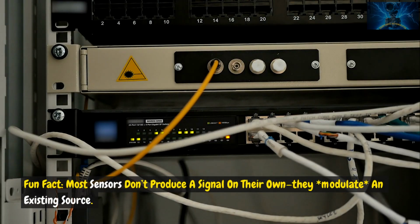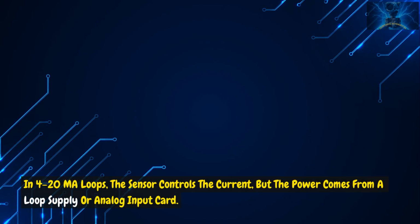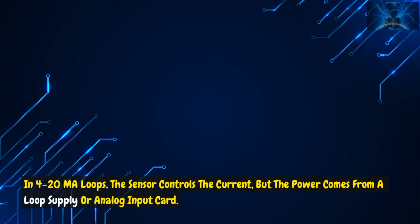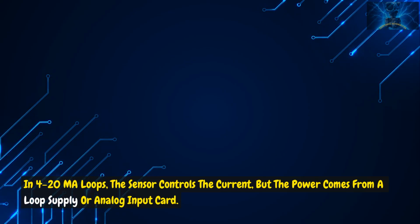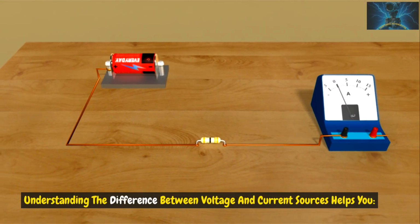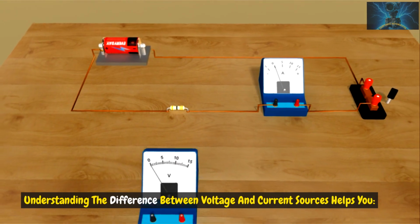Fun fact: most sensors don't produce a signal on their own. They modulate an existing source. In 4-20 mA loops, the sensor controls the current, but the power comes from a loop supply or analog input card. Why it matters. Understanding the difference between voltage and current sources helps you: